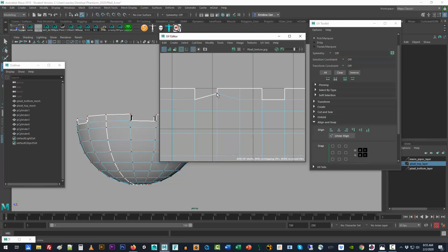So what we want to do is align this UV with the others. That's kind of our point of reference, but it's relative. It's not absolute like snapping it to the grid. If we snap things to the grid like we can in the modeling window, that actually doesn't help. So all these quadrants are a bit weird. We don't really want them. What we do want is to take this UV and say, okay, I need to straighten it out according to its brothers and sisters here around it.